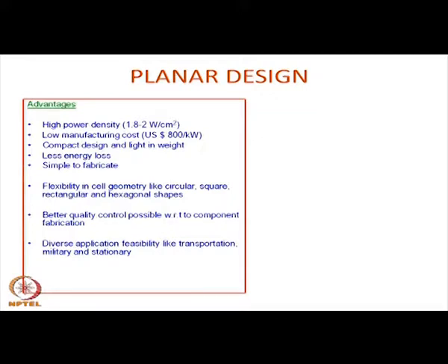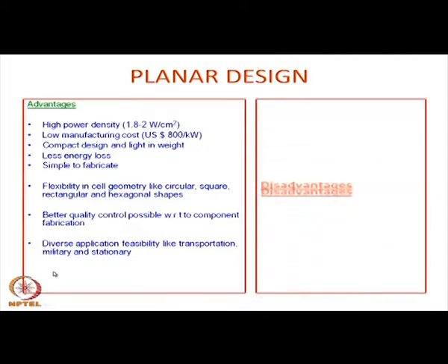So, in addition to the motive power, the basic power is once again the IC engine, but today's automobile needs a lot of electrical power for running many electronic gadgets, and therefore, that electrical power can come from the fuel cells. So, that is what we call the auxiliary power unit, and that auxiliary power unit has been demonstrated with solid oxide fuel cells. This has not been possible with tubular designs.